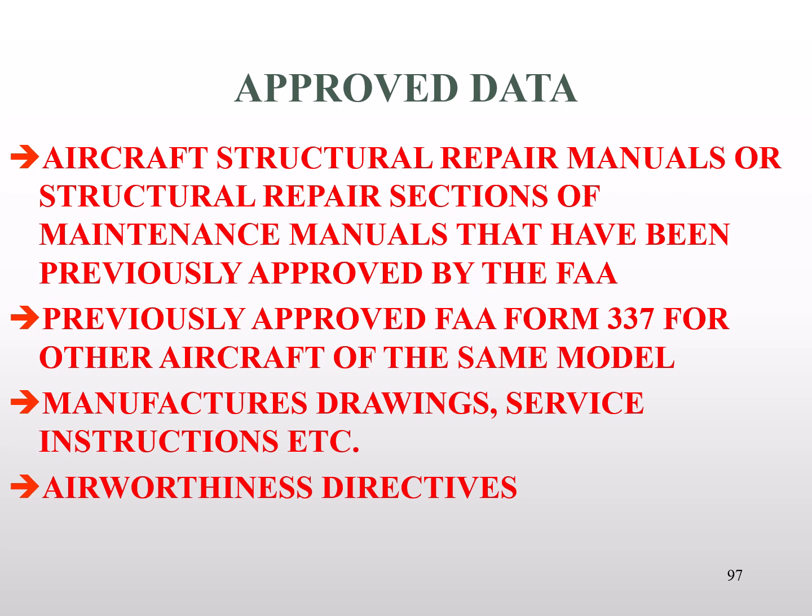Now, the other type of data that we're going to look at is acceptable data. Hear me when I say this. You never move forward with a repair unless you're working with approved data, previously approved data. Acceptable data has yet to be approved. We do not have permission yet. We're just using something that is generally found to be acceptable, but with acceptable data, we're going to be asking permission to use it. Approved data, we already have permission in our hand.